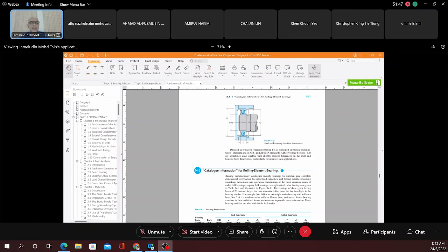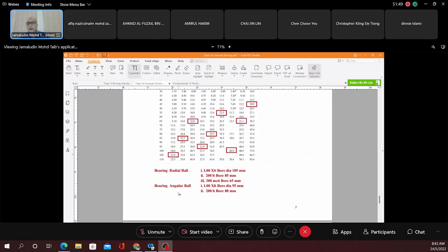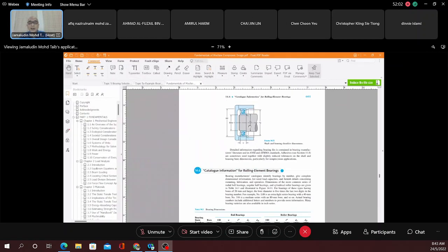For example, in this example here, you found 1.5, you got 45, then the shaft, and after that you can use the suggested diameter by, for example, the ds here. All right, then with all the inner bore diameter with the radius, check whether the shaft is failing or not. That's the other way around. And that means the shaft will be finalized. That is fine. That will be for the project.